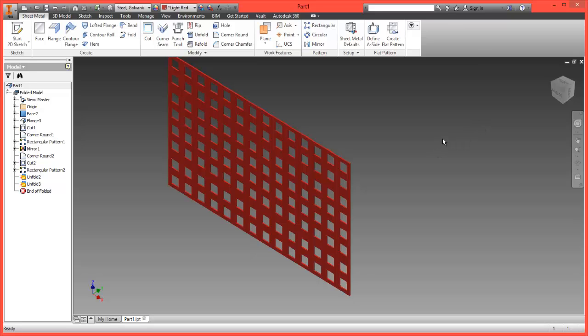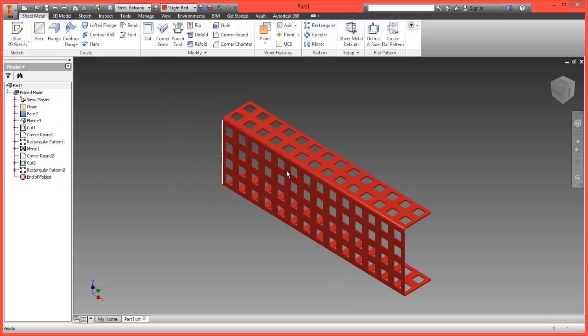So this is a really good way of effectively undoing a 3D sheet virtual net along all its bend lines. And this is really how you can see how you're going to actually manufacture these using a plasma cutter or a laser cutter or any various different process that you have available to you. My stock material will arrive like this without all the little holes in it. It will be plasma cut, all the little holes will be cut in, and then of course it will go around, and using my own processing tools I will then be able to bend and form this component into the VEX component parts.